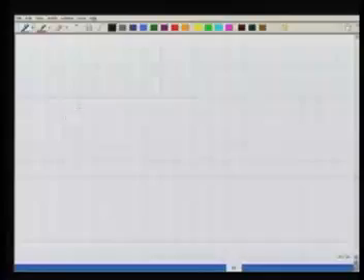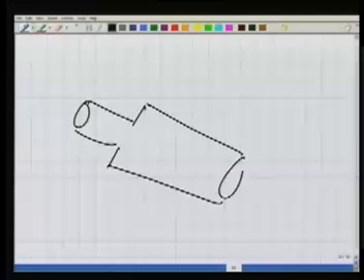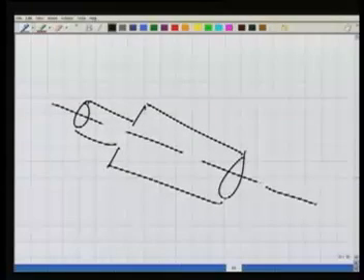How will we do it? We will do it using the leveling screws. You just use the leveling screws and tilt your level in such a way, while you are looking through the eyepiece, that it is now bisecting RA triple dash on that staff. If you do it, what will happen to the bubble tube? The bubble tube will go out of the center, because you are bisecting a different point.